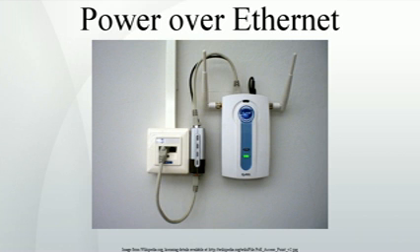When the device is a switch, it is commonly called an end-span, although IEEE 802.3 refers to it as endpoint. Otherwise, if it's an intermediary device between a non-PoE capable switch and a PoE device, it's called a mid-span. An external PoE injector is a mid-span device.